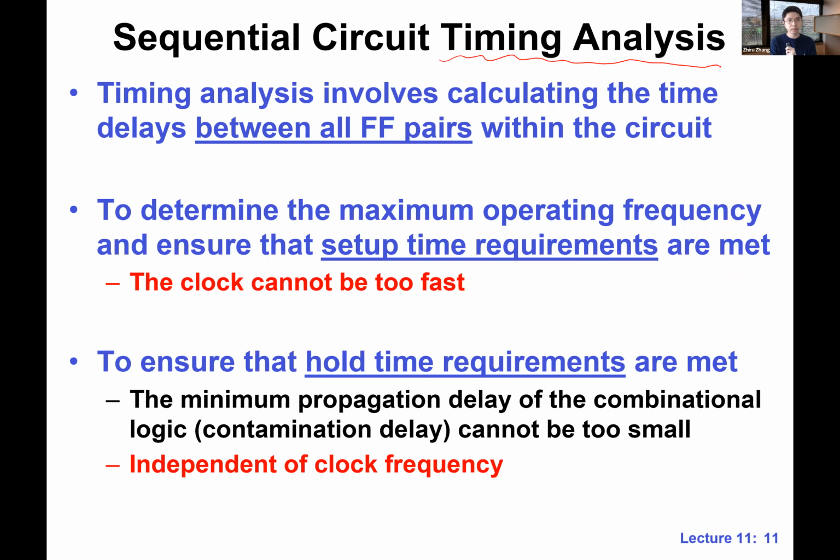And we have something called hold time as well. Hopefully this will be more clear later on. We need to look at the minimum propagation delay when we analyze the hold time, and we look at the maximum propagation delay when we look at the setup time. Interestingly, for hold time, when we analyze it, it's independent of the clock frequency. When we analyze the setup time, we very much need to determine the clock frequency.